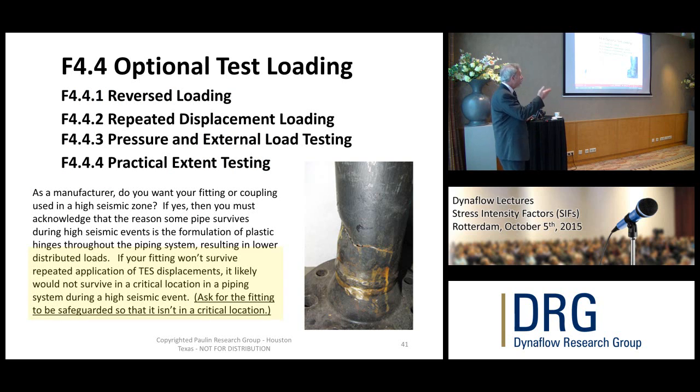Another factor that's involved with sustained load testing, that we're trying to bring out, that people have made very significant mistakes in, is that piping survives earthquake, it survives water hammer, and it survives errant calculations because it's ductile. The seismic loads that we're using are way underestimated for real seismic events.